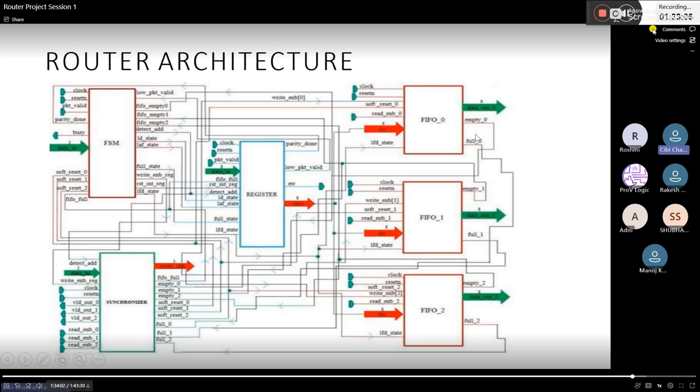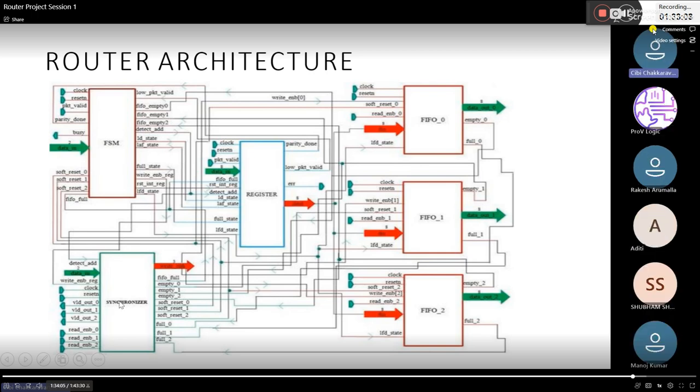If it is doing some other work or it is busy at that time, when we are giving input packets, it will not enable that read signal. That way we can confirm that it is in some other operation, or we can give a busy signal. Then we can understand that our FIFO is in a busy state, so we can pass the packet some time after. Other than that, if some packet it cannot handle, no problem. That is what you asked.